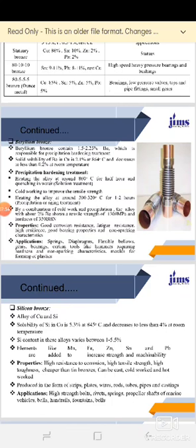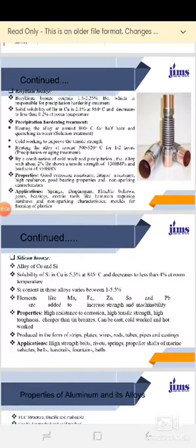The properties are good corrosion resistance, fatigue resistance, high resilience, good bearing properties and non-sparkling characteristics. Its applications are springs, diaphragms, flexible bearings, gears, bearings. Certain tools like hammers require hardness and non-sparkling characteristics, and molds for forming plastics.